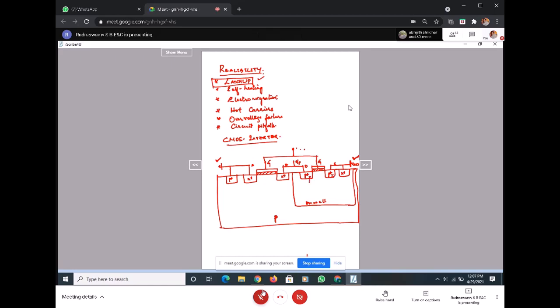So you can see that this is P, this is N, this is P. All of you are with me? So I have one BJT, a PNP BJT, existing from the N well up to this P substrate. So P, N, and P. Similarly, there is another BJT. See, this N plus and this N plus: this is N, the substrate is P, and again I have an N here.